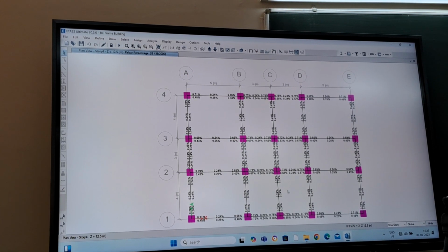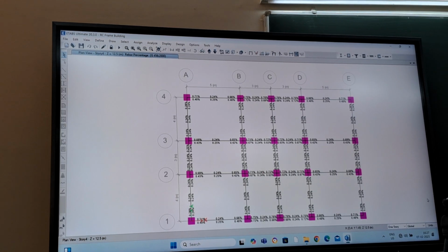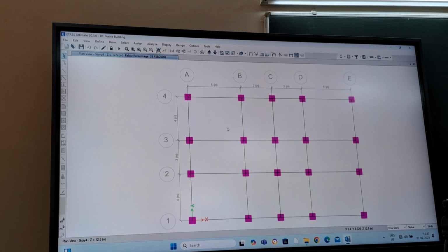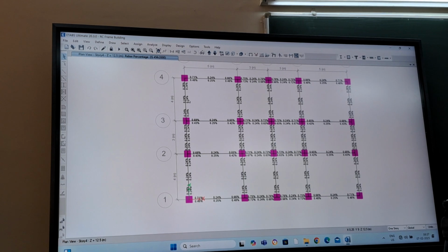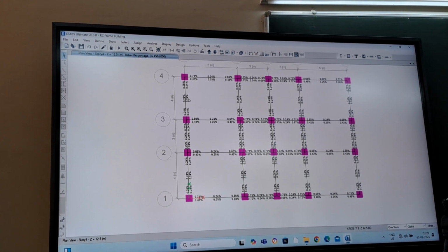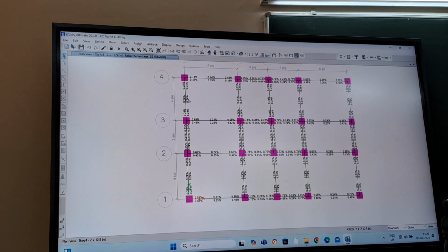So in this story, if you see, in the x direction all the beams are acceptable. Means reinforcement is within the acceptable range. But what about y? Which is less than 0.5. Means in the y direction you can reduce the sizes a little bit. Okay. So you do that and cross check once again what the requirement is coming to be. This is how we check.